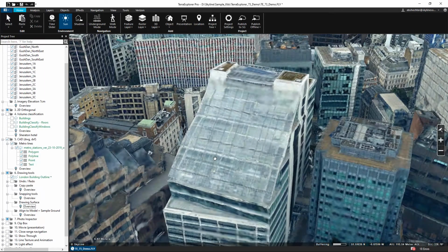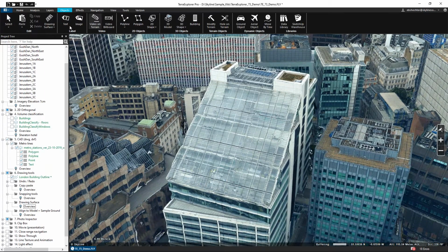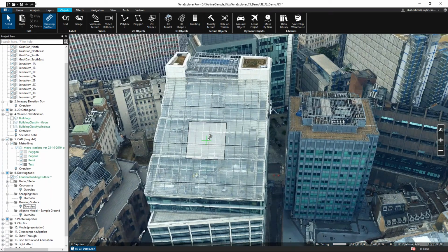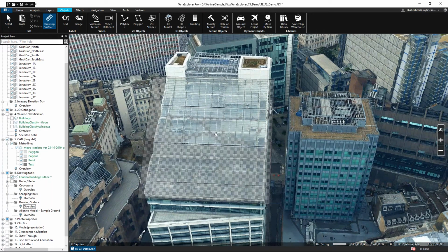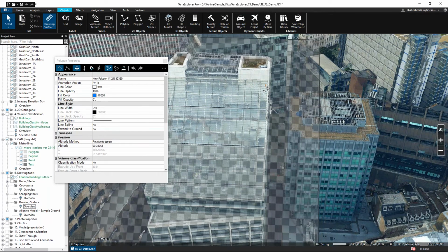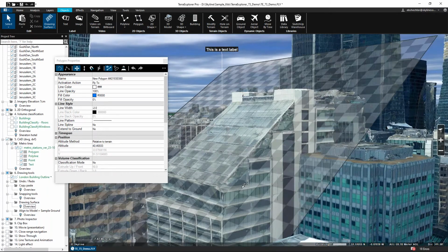And the drawing surface option, let's put a drawing surface. So if I want to, let's say, draw on the surface, but I don't want to necessarily snap to the mesh directly, but I do want it to be aligned to the surface, I can create a drawing surface here. And then you see when I go to draw, it dynamically moves to where it needs to be. It extends the surface in the direction.